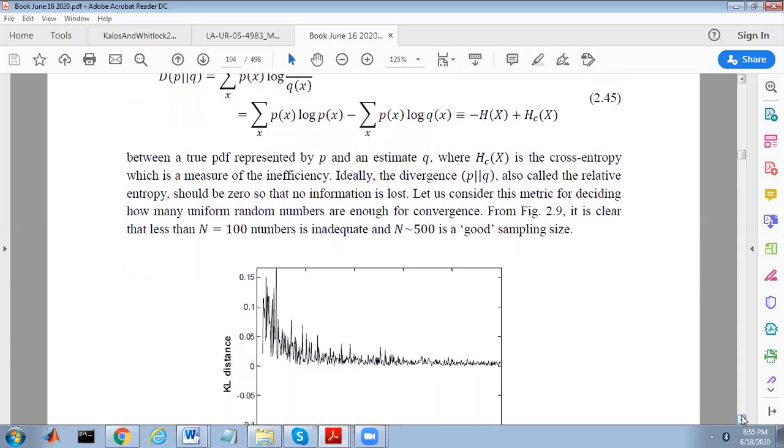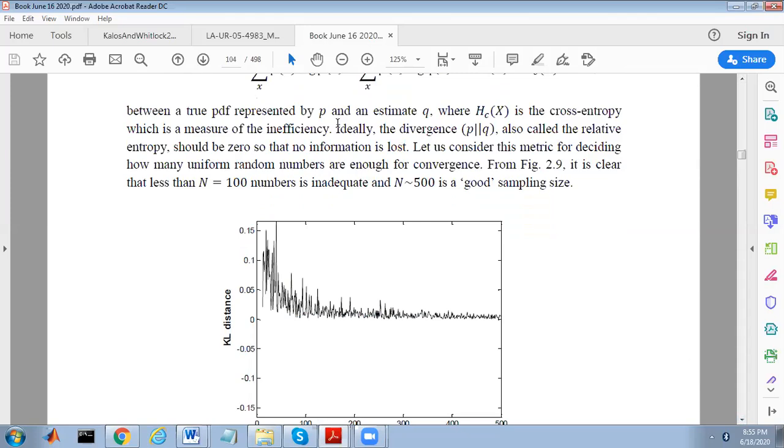How bad are we? Because remember when you do deterministic finite difference or finite volume or anything deterministic, you say that you have a converged solution because your answer won't change if you take 100 more steps. Now here in stochastic processes, you never do achieve a final answer. You always go up and down because there's always noise, there are fluctuations. So that is why we have to see that we've achieved stability.